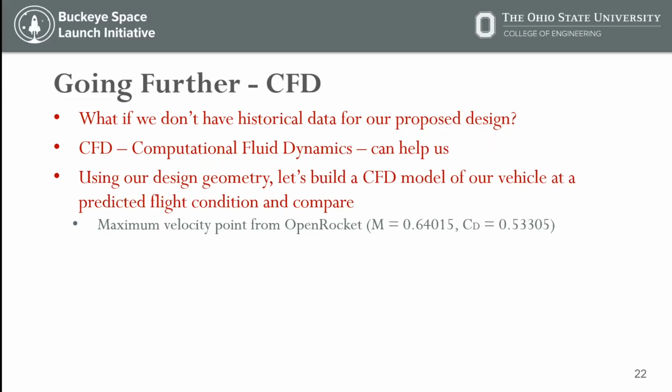And then here's some information so we understand what we're looking at. The maximum Mach number predicted by OpenRocket is about 0.64. Again, in that subsonic regime, it's not even transonic yet. And the drag coefficient that we're looking for is around 0.5. We're looking at 0.53.